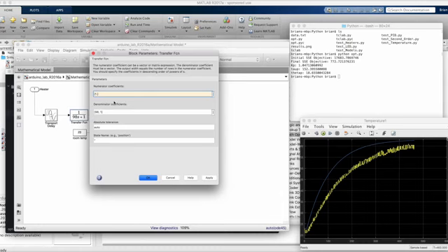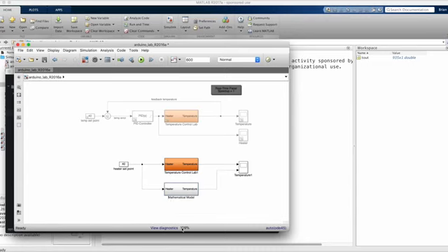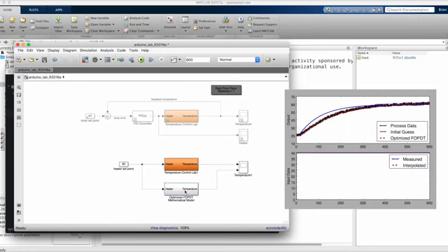Now, at least for a while, we don't need our hardware to design a controller. We can use this new model to perfect our PID controller, try some feed-forward control, or build an optimal model predictive controller. And we may find later that the first-order model doesn't accurately represent higher-order dynamics and we need to improve it, and then we will just do that.